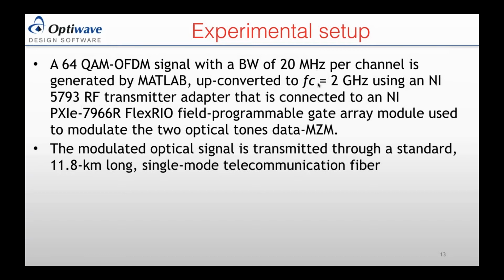And then you can also tune or choose the carrier frequency of your LTE signal. Because of the limitations of our equipment, the NI has a maximum reception bandwidth or frequency of 26.5 gigahertz. So we decided to use 24 gigahertz instead of 30 gigahertz, just to give an idea of the near millimeter wave signal, and how we can linearize it.